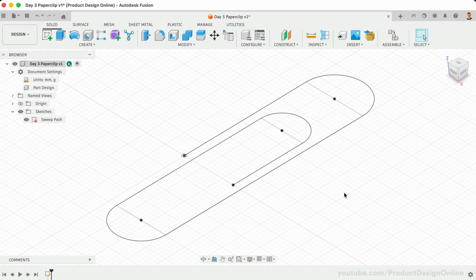To create a sweep that follows this paperclip shape, you need a sketch profile. In this case, we'll use a standard circle as a paperclip is a round piece of steel bent into a loop shape. Since you followed the best practice of starting at the origin point, you can sketch on the front XZ plane to create the profile.